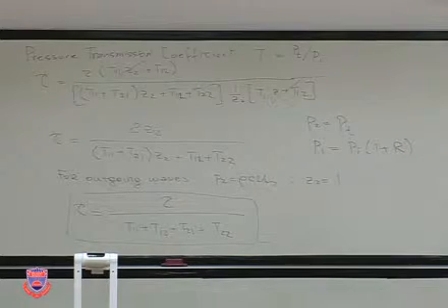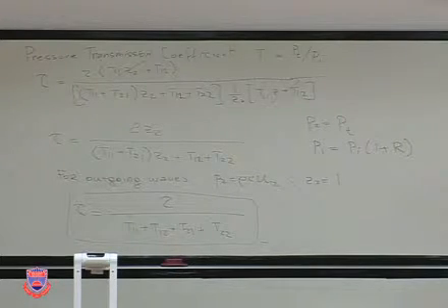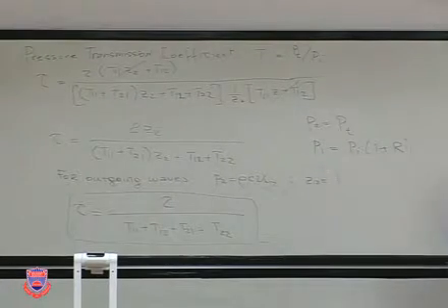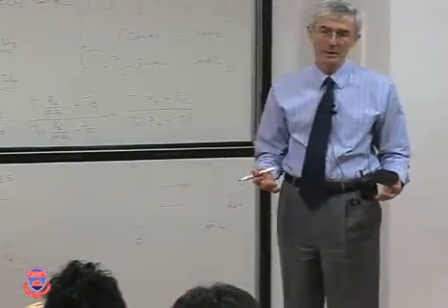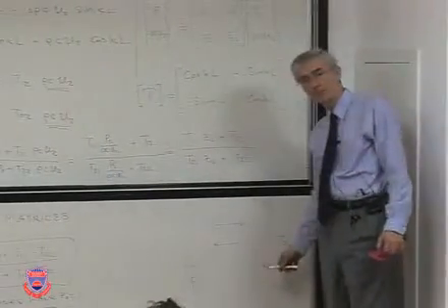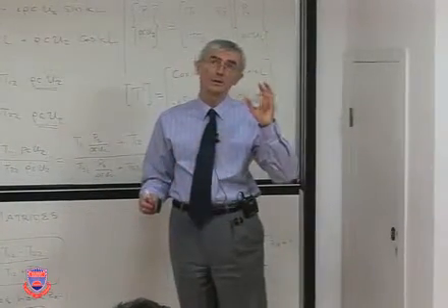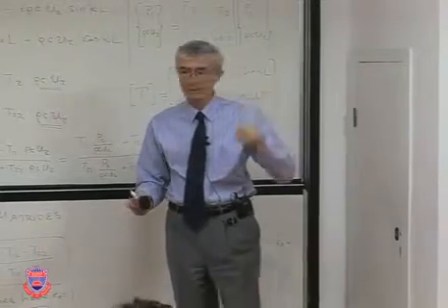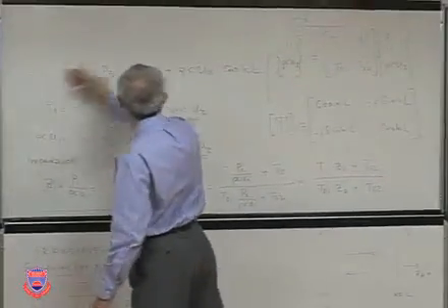Now, something that you have not yet really dealt with, and that is the absorption coefficient. What would it be? What is an absorption coefficient in a system like this? Absorption coefficient is the portion of the sound wave that is not recoverable, that turns into heat, basically. So it usually happens when you have a complex impedance. So it will be the difference between incident, and reflected and transmitted. So that's what's lost. So let me just quickly describe the expression for it.